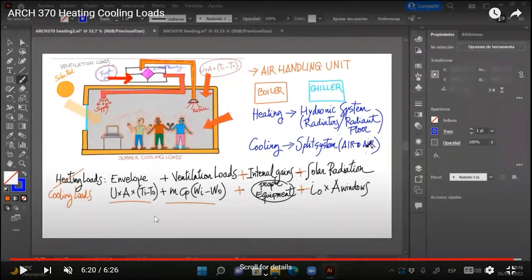And the solar radiation, the solar radiation design matters because we have to maximize the solar gains in winter and minimize solar gains in summer. And this is about architectural design. It's not about anything else. Yeah, we can use a technology with things that move so that in summer they let the sun in, and in winter, not the other way around. But I don't believe in things that move in buildings. So let's design something that is fixed and it works well in winter and summer.